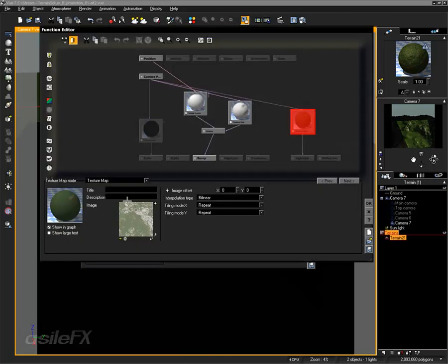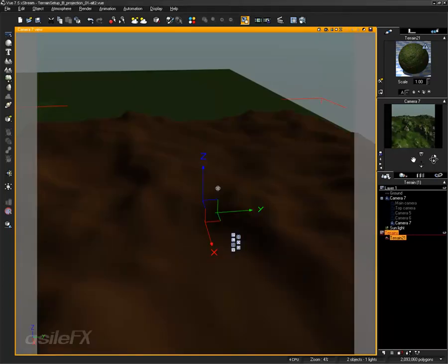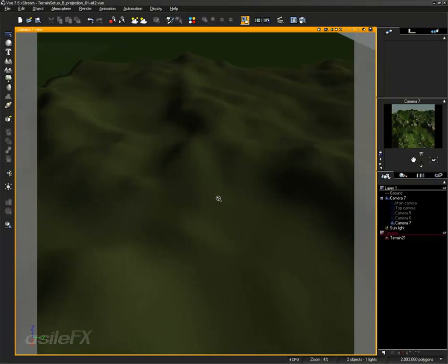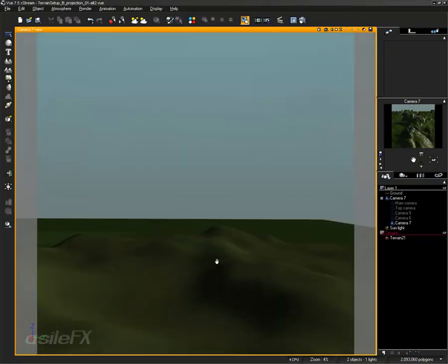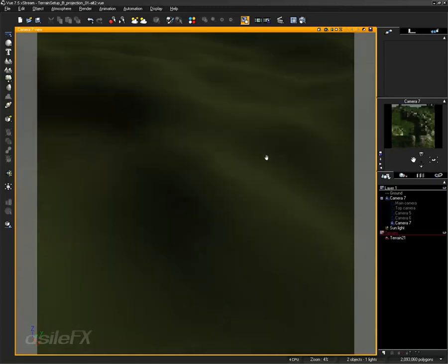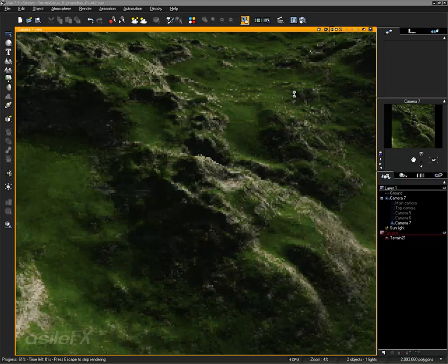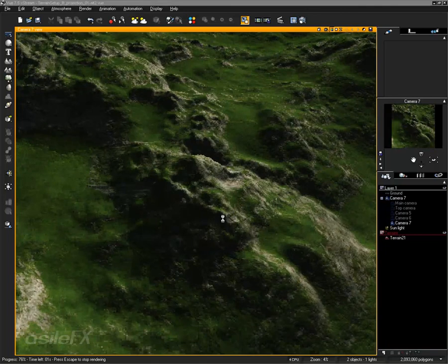Because this did change the OpenGL preview, I am going to set this back to repeat. If you want to get rid of the seam, you could set it to mirror. And that way, just in case you get outside of the bounds of the camera projection, then you've still got some detail. And you won't have a seam. But if we take a look over on some of the side areas that didn't have a direct projection, you are going to notice some stretched zones.